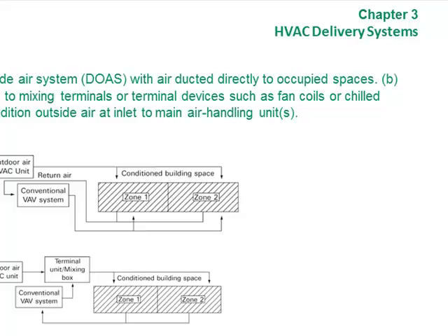What page is that one on? Just so I can look at it. That'd be on page 83. Yeah, it's sheet 3.4. Ah, there it is. Constant volume multi-zone system, a triple zone, double deck multi-zone. So you have different zones and you can control them by mixing the air. Oh, it's hot and cold. Yeah, you mix the air. It bypasses over both coils, right.